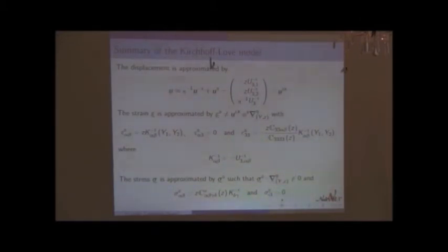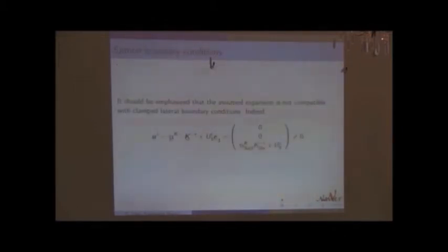So this approximation of the displacement field fulfills the clamped boundary condition. But you could use the small corrector related to the out-of-plane Poisson effect to have a better approximation of the displacement field I just discussed. Okay. But the problem is that first you don't know this U3-1, which is the higher order deflection. And this guy doesn't comply with the clamped boundary condition. It's not 0 on the boundary, because the total curvature tensor is not set to 0 on the boundary. Okay.